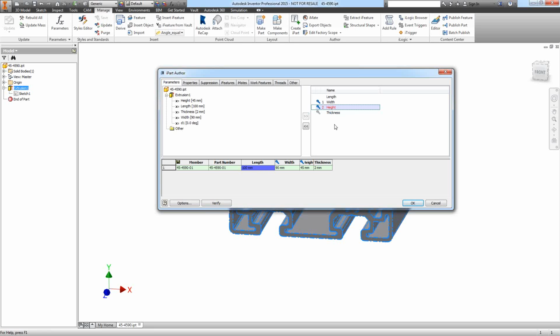So I have a single row here. That's all I needed for this case. It might be a good idea also to put in some things like a stock number and maybe a part number. Well, I guess the part number is already there. So that if you want this information to come out onto the parts when they're placed, say for bills of material, that you have that already in place.